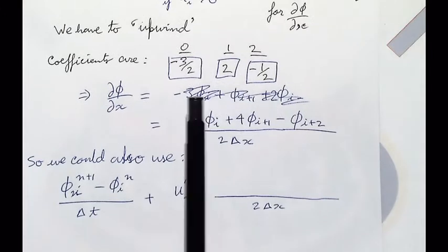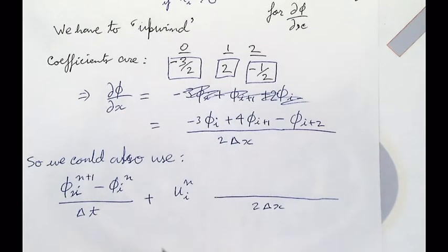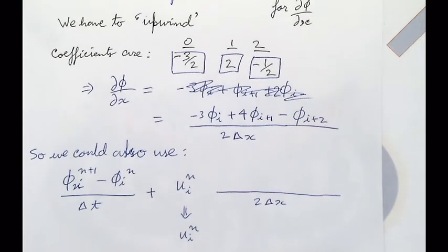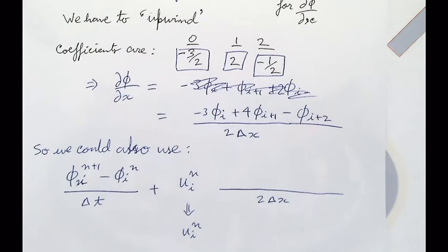Okay. So instead of using this first order term, we could have used this. Again, here we are biasing to the right. So what should u be? Is this less than 0 or greater than 0? It's upwind, right? It has to be positive. If u is positive, which direction would you bias in? Left or right? Information comes from left to right. Yeah, so biasing means...